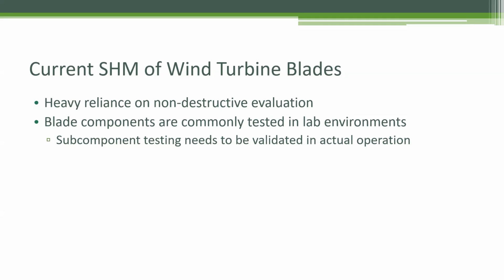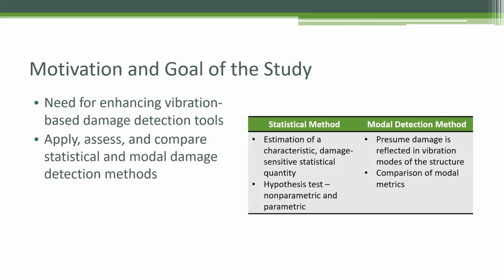Existing structural health monitoring approaches rely largely on non-destructive evaluation techniques. Due to difficulties of on-site testing, blade components are typically tested in a lab environment. Although this is efficient, it needs to be validated in actual operation. Thus, enhanced applicability of vibration-based damage detection tools is needed.